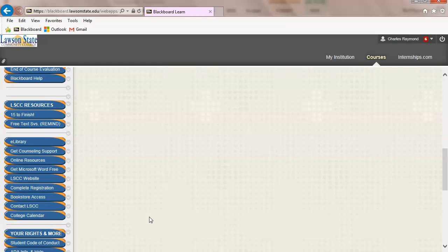So what voltage do thermostats in your house operate off? We'd be getting people killed all the time. 24, good. 24 volts AC. It operates off 24 volts AC, but your compressor and your fans operate off of 240 volts AC. So how can we take 24 volts AC and control 240 volts AC? Relay, good. So the relays have 24 volt coils on them, but they control what? 240 volts on your motor. And that's what we're going to do here.